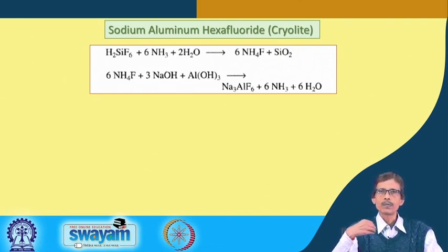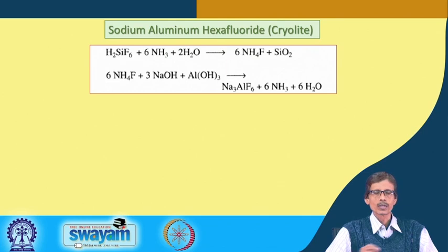Anywhere you can have the corresponding very low grade or very poor quality aluminum sample, you can convert it by alkali treatment in the basic medium. So, alkaline treatment of that particular one gives you simple aluminum hydroxide. Now, that aluminum hydroxide will be used for the preparation of cryolite. So, your aluminum hydroxide will be the typical source for making your synthetic cryolite, because that cryolite we can use for aluminum production, the pure quality of aluminum production through electrolysis.